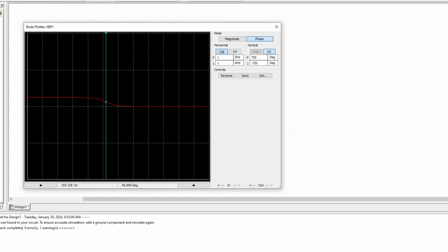That is why the 3 dB point is more critical in finding whether the signal is attenuation or amplification, or what is actually happening, because that is where the critical frequency lies. It has two critical frequencies generally. If you combine the lead and lag network, the same thing will apply for the lag network.